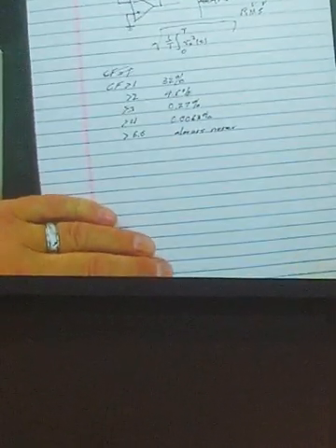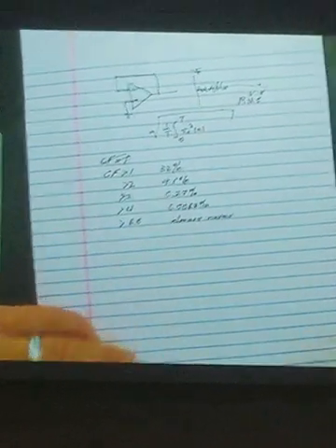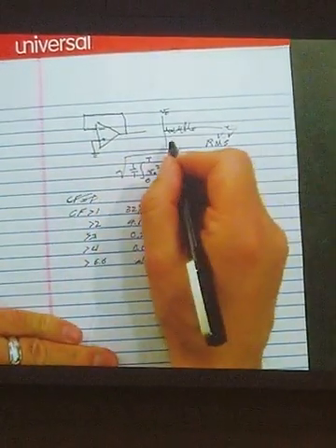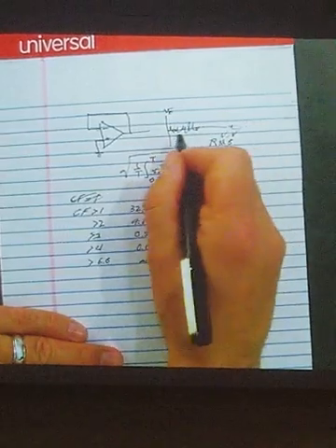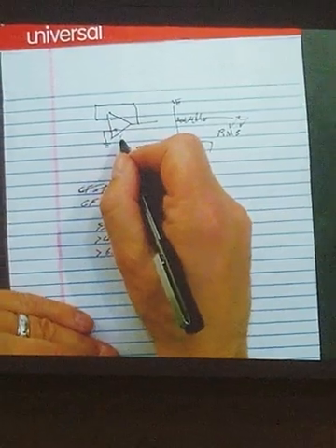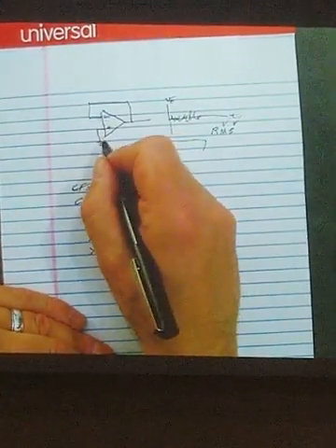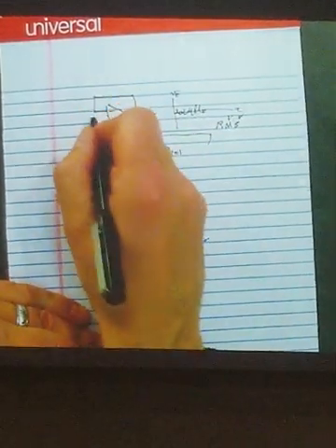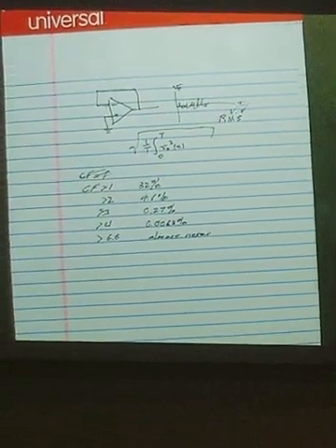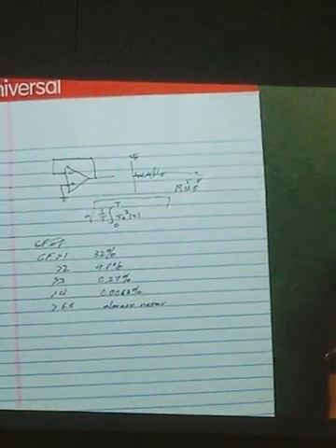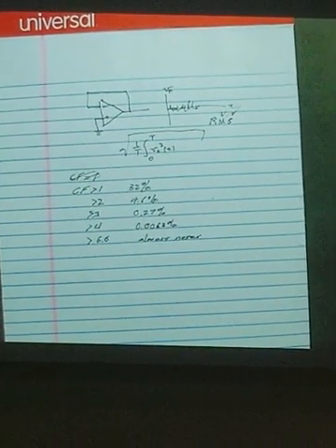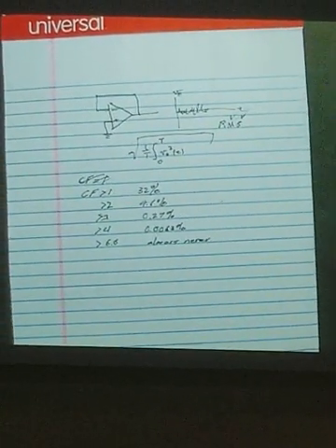But the reality of that signal is that it is band limited, right? And certainly in the case of op-amps, if you did an FFT of this and analyzed its frequency components, you would see that a 741 only has, when set up as a unity gain amplifier, a bandwidth of, no, the gain bandwidth product of a 741 is about a megahertz.